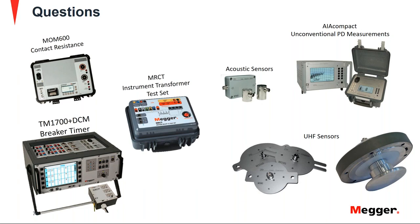If you have a UHF measurement and you have picked up a signal and you know you have partial discharge activity, you can then at that point transition to acoustic measurements, which allows you to localize that defect again. And that can be used, as we see on the slide that's left up here, that AIA compact, you can use both UHF and acoustic sensors.